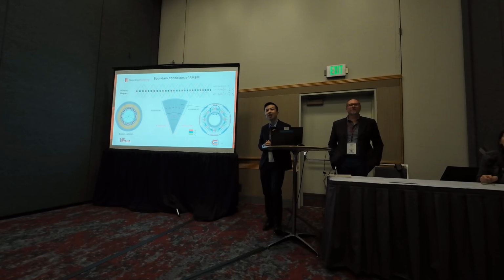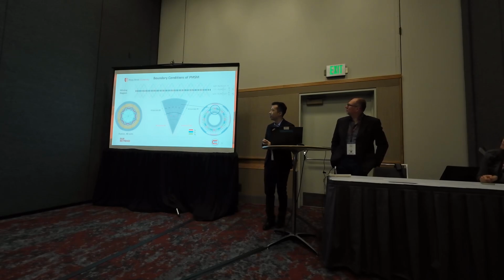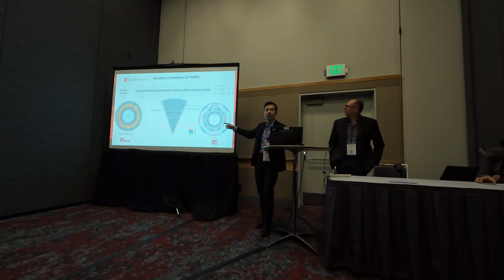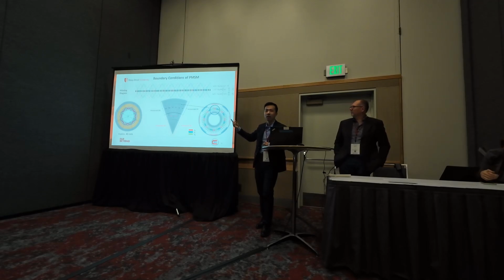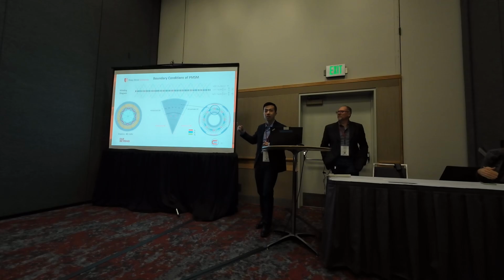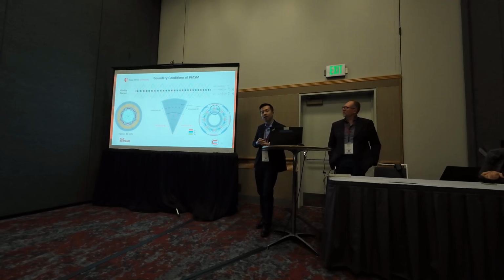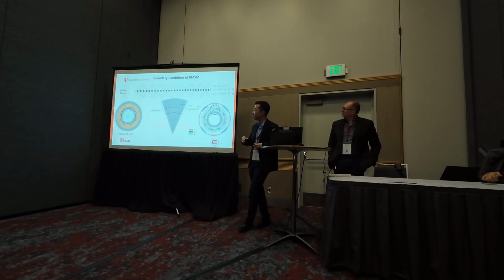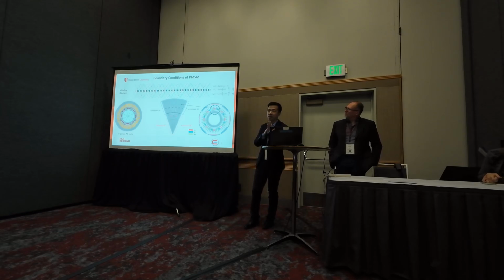So why did you choose the eighth sector to run the simulation? Is there any reason for eight? It doesn't really matter. That's just a reference model. We have various reference models. It's not just 8 poles, 48 slots. It can be some other, like 6 poles and 36 slots. The same result in the topology? Not the same. Because different machines have different design domains, different sizes of design domain, and the boundary conditions might be the same, but the design domain is different.